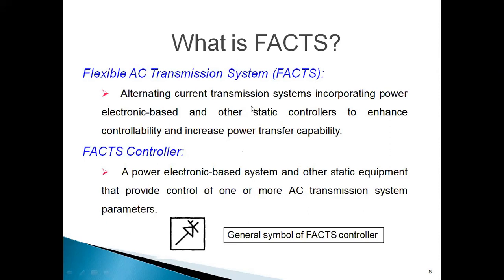Now I should know how I can achieve this. What is my objective? That I'm clear about. How should I achieve it? That is my second question. For that, I should know the relationship between the power system parameters. I told you that all the power system parameters are interrelated: P-delta, Q-V. So how are the real power and reactive power flowing through the transmission line related to the other parameters, in terms of voltage, reactance or delta? That is what we are going to see now.